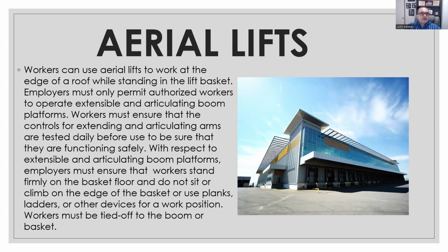Workers must ensure that controls for extending and articulating arms are tested daily before use, to confirm that they're functioning safely. With respect to this type of booms and lifts, employers must ensure that all workers stand firmly on the basket floor, do not sit or climb on the edge of the basket, or use planks or ladders or other devices to gain a work position. Workers must be tied off to the boom or basket. So you must be tied off with fall protection, the same as you would be in any other instance on a roof. You cannot just be in the basket and be able to fall out.